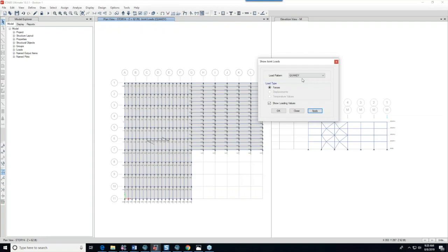But when you have a semi-rigid diaphragm, and let's say the diaphragm is just a metal deck with no concrete fill, so it's quite flexible, we don't want to apply it to a single joint because you could get some local deformation and high stresses at that one joint. So we arbitrarily find 10 points and apply those loads to the structure to help distribute the loads out. Now, it's not necessarily perfect. It's certainly not as distributed as the seismic loads, but we think it's a reasonable approach.